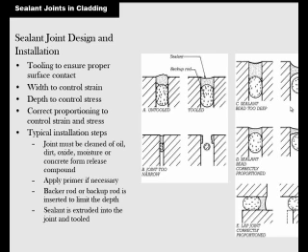And then you apply a primer. A backer rod is this piece right here, which I think is a piece of foam they just stuff in the back of the joint. And then the sealant is extruded onto the joint and tooled. If you don't put the backer rod in there, obviously you might just squirt into oblivion. So that's why it's there.